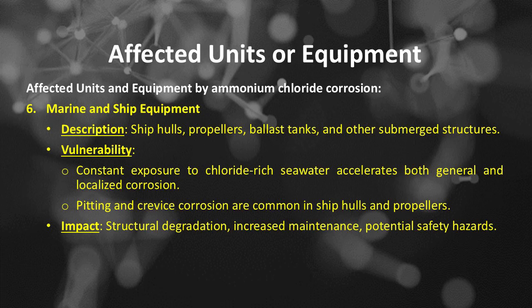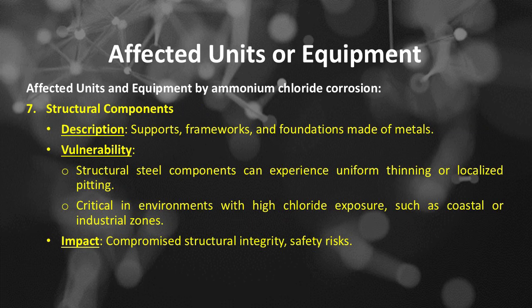Number 7 is structural components. Description: supports, frameworks, and foundations made of metals. The vulnerability of ammonium chloride corrosion to structural components includes structural steel components can experience uniform thinning or localized pitting, critical in environments with high chloride exposure, such as coastal or industrial zones. The impact: compromise structural integrity, safety risks.